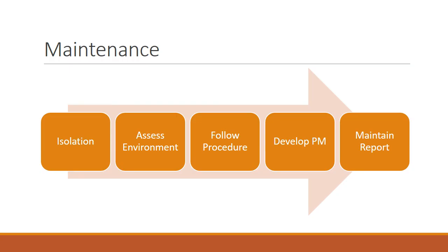One of the most important things that you should do is to find out the lubricant that's being used by your switchgear. In a sense, you should also look at what the actual brand is that you used. Because different brands and manufacturers have different kinds of ratio of the fluid that they use. And employing the wrong product would void the warranty of your switchgear, as they are usually maybe less effective than the materials used by the manufacturer of that said switchgear.